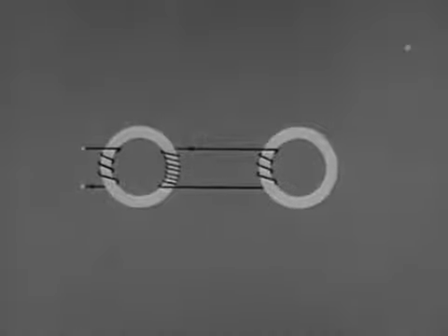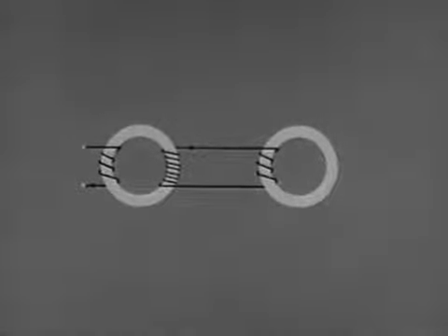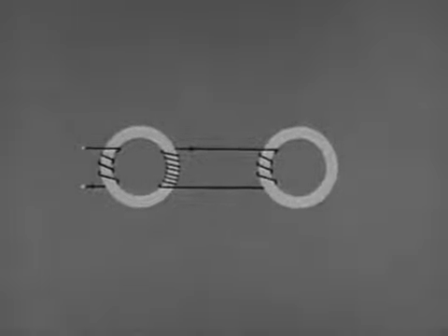By connecting in a second core on the right, we can see more clearly what the problem is. Now, the first core's output winding is directly connected to the input of the second core. This input has been wound so its polarity is the same as that of the input of the first core. The dot side is below.